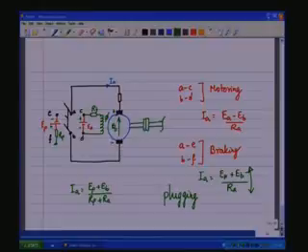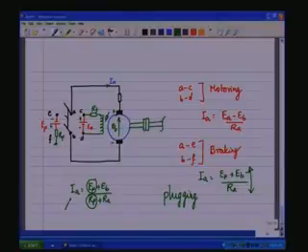So, you can adjust the value of IA to a required value, whatever the armature winding gauge capability is, for a very short time, by adjusting the EP value, which means this voltage, and adjusting the RP value, which is this resistance. This can be used to design the armature current value during plugging. Okay. Now, this can bring the motor to a very quick stop.